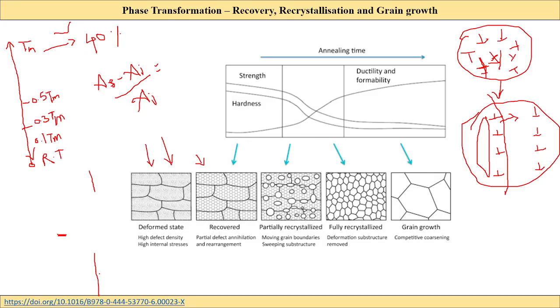So at one point they will coalesce. That means these two planes will get attached, right? That is nothing but a total plane. That means the two dislocations are being annihilated, right? The two dislocations disappear because the positive half plane from above and the half plane from below, when they come near to each other, give us one total plane.